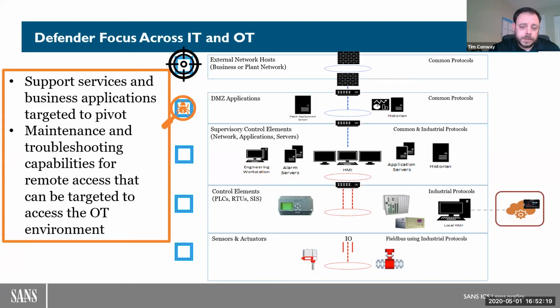Moving down into the environment further, again, looking at the support services that are offered for patch deployments, for read-only data historians, for management and leadership view of operational performance and tuning, looking at maintenance and troubleshooting components that are up at that level, where they're pushing antivirus signatures down into an environment, or pulling logs out of an environment, that four-legged firewall where you have a DMZ that handles egress traffic and a DMZ that handles ingress traffic into the lower levels of the environment that are secured higher.